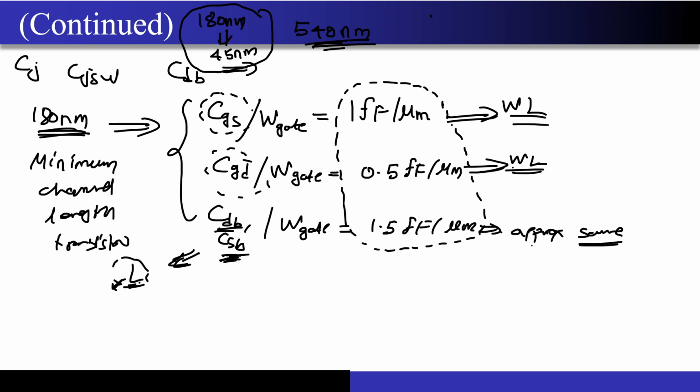So now these are good enough for first-hand calculations of finding out the poles and zeros, so that you don't have to do a lot of lengthy calculations, and then from here calculate the poles and zeros and see how much your phase margin is getting degraded. Because remember, even though your poles are lying outside the omega UGB, how far away they are from the omega UGB will matter, because your phase margin actually depends on that factor.